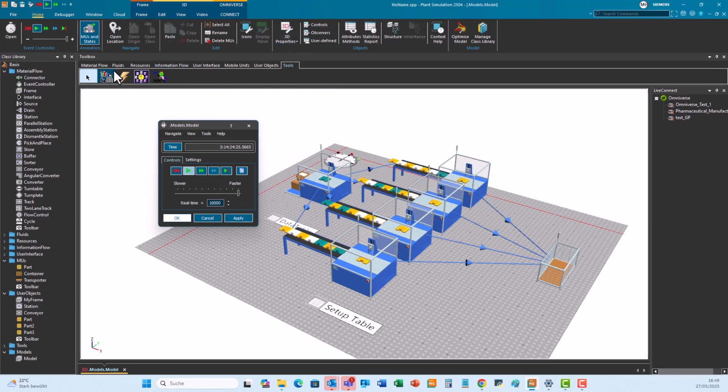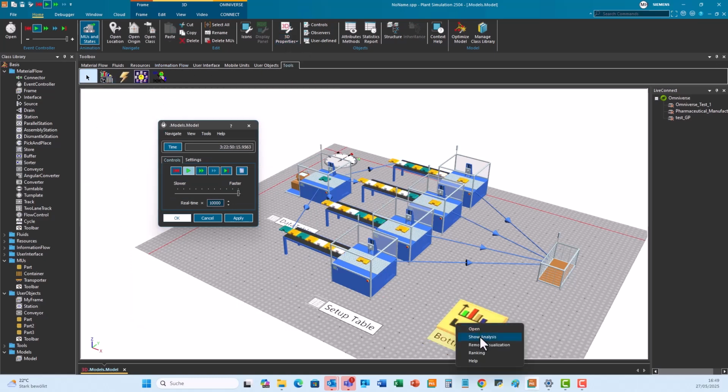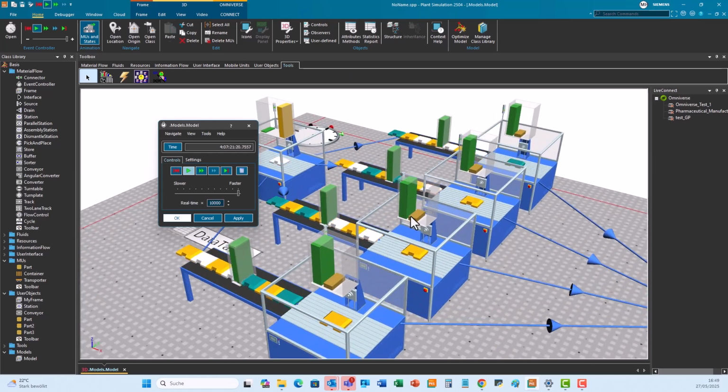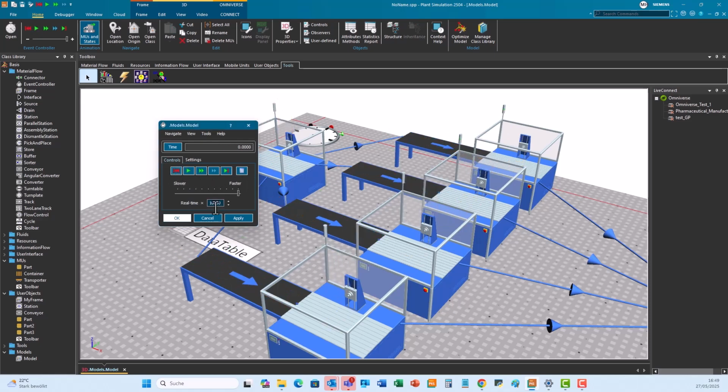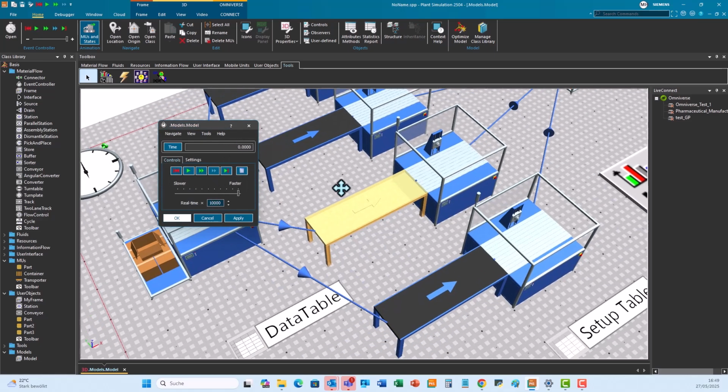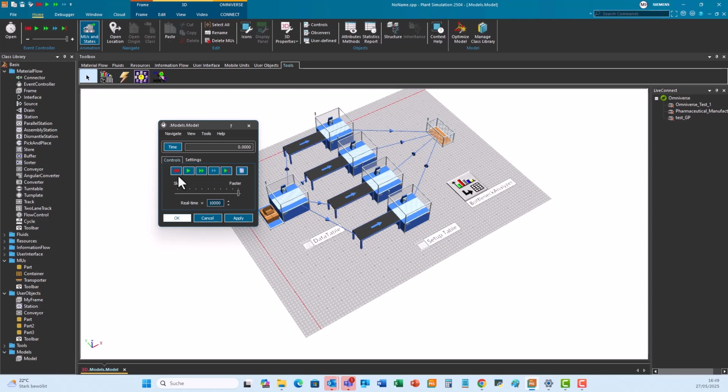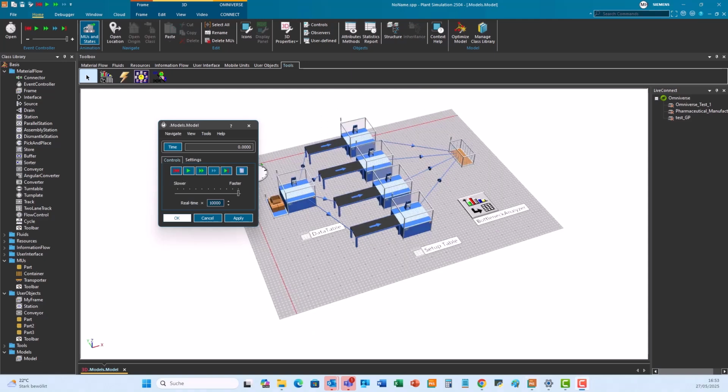When we insert our bottleneck analyzer, the bottleneck analyzer is scanning the whole system and shows with those green bars the utilization working, this is good, and brown, this is the percentage for the setup time. So this station is reduced in the percentage of working time for the setup. And this would be our potential for optimization using the genetic algorithms. If we want to run an optimization now, we simply plug in our genetic algorithm module and tell it to maximize output over 5 days by tweaking the production sequence.